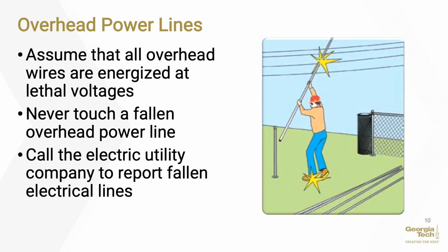Working with or near power lines can expose workers to electrical hazards, but these dangers can be avoided through safe work practices. These practical steps can prevent injuries from contact with power lines. Conduct a hazard assessment to identify and address potential safety hazards before work begins. Ask the electric company to de-energize and ground overhead power lines. Educate workers on safety procedures and requirements. Know the safe working distance for workers and equipment. Use non-conductive wood or fiberglass ladders. Wear personal protective equipment such as rubber insulating gloves and insulating sleeves and industrial protective helmets.